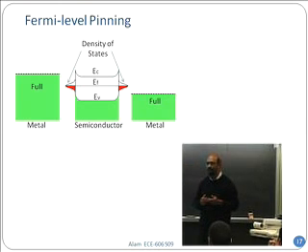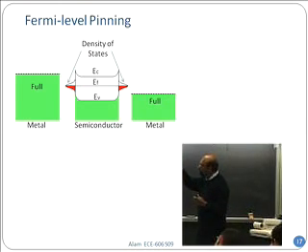Like you have a lot of traps, as if you have a lot of doping in the end of this region. Because if you solve for the position of the Fermi level in the presence of the surface states, then you will see the Fermi level is very close to the middle because we have so many traps. As a result, you see that the red region I have shown with sort of a Gaussian curve is somehow to represent the presence of the surface states. And when you have that amount of surface states, it pins the Fermi level to the middle of the band gap.